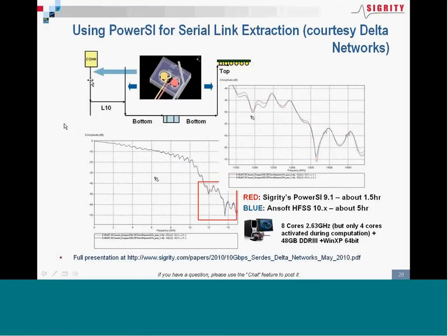Now the extraction that we did for this, obviously Sigrity has a lot of technology in the form of PowerSI, which is an industry standard tool for power integrity analysis to extract the detailed power distribution systems. It can also extract them coupled together with the high-speed signals to extract this all in one model from your layouts. This is what was used in this case.